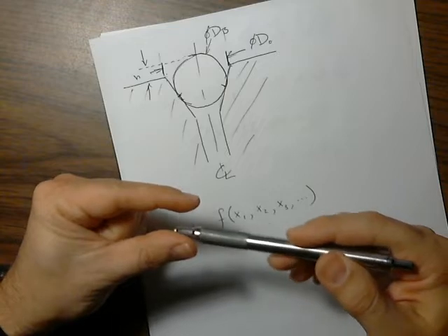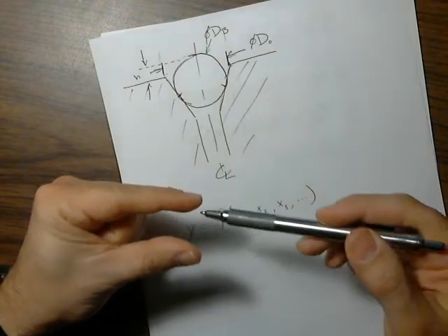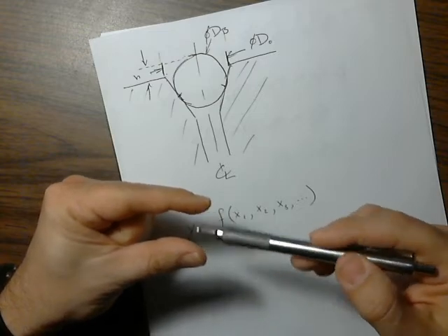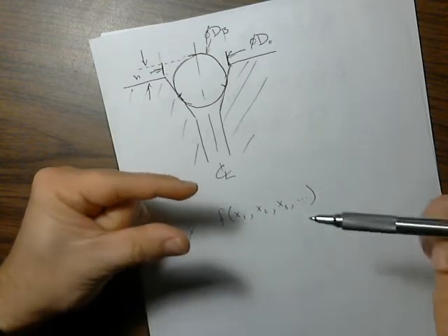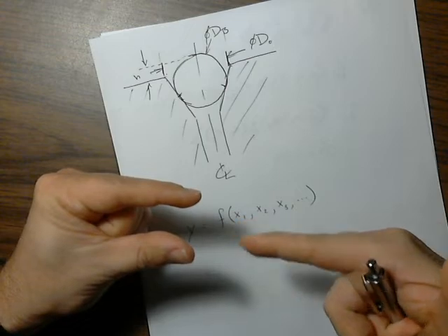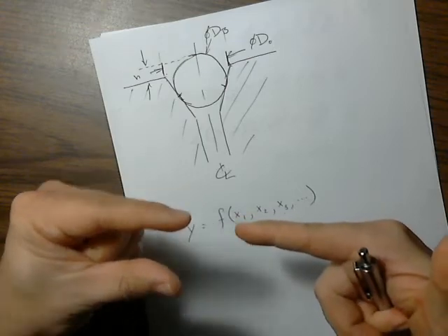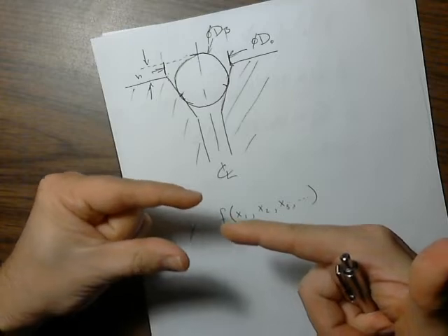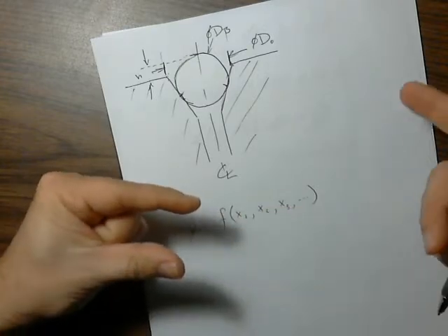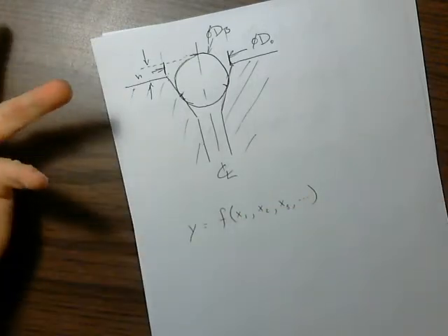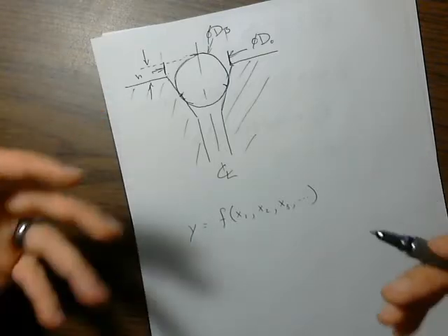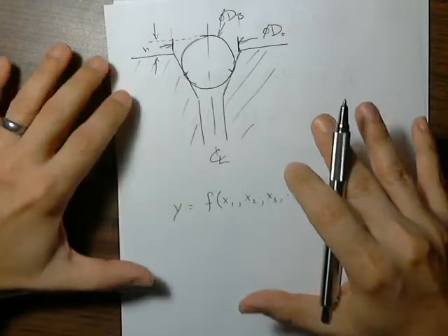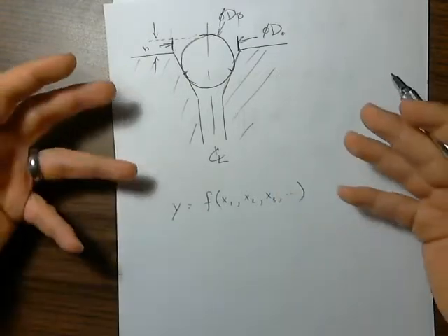Well, that capacitance is a strong function of the humidity, but it's also a strong function of the temperature of the air. So you have a temperature sensor hanging out over here measuring the temperature, and you've got this capacitor over here measuring capacitance of the air, and from the two of them you can calculate the humidity. Well, what's the confidence interval on that calculation? This analysis that we're going to use today is how you figure that out.